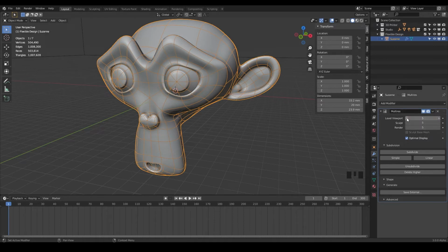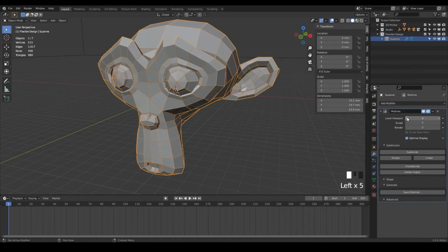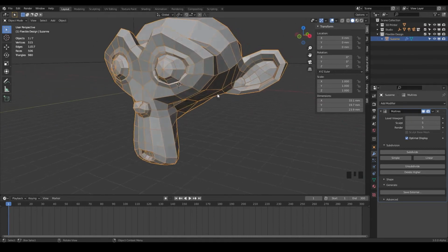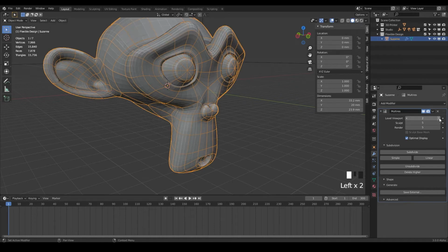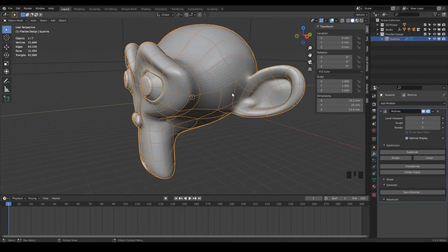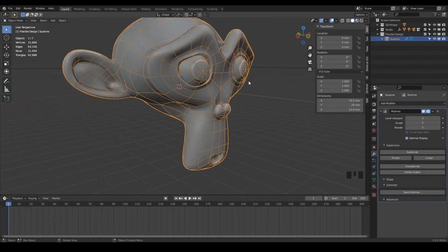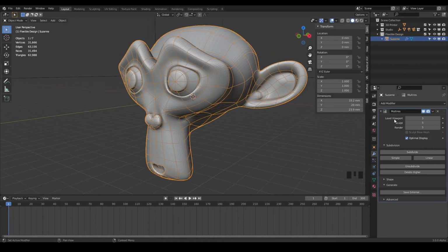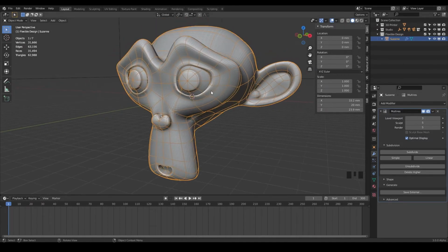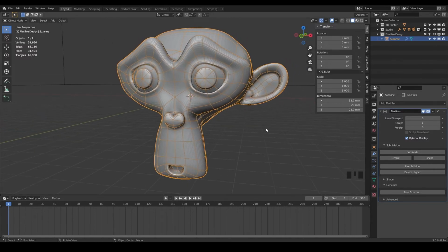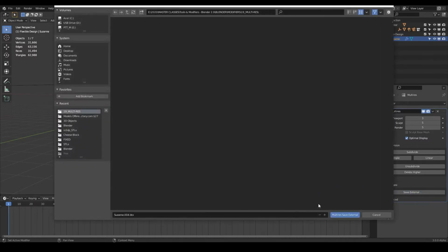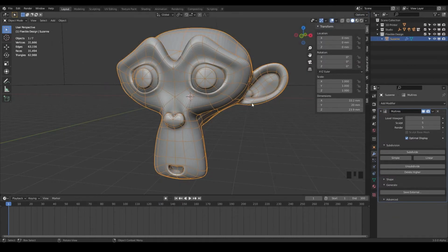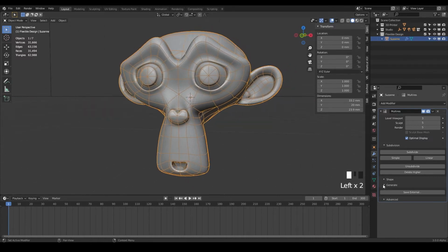So now what's really cool is you can essentially crank back down to almost the original design here. So Blender's kind of reverse engineered some sculpts. That can be really helpful if, say, you're bringing in something from ZBrush or from another sculpting program. This generate tab, the button's gone now, but it will essentially give you those levels of control back on a super detailed high poly model. So that is what the generate tab does here. And I guess you could save it. I've never done that, but you could, I guess, save your multi-res there and use it for an external program, but I'm just going to stay in Blender here. So that's what the generate drop down tab does.